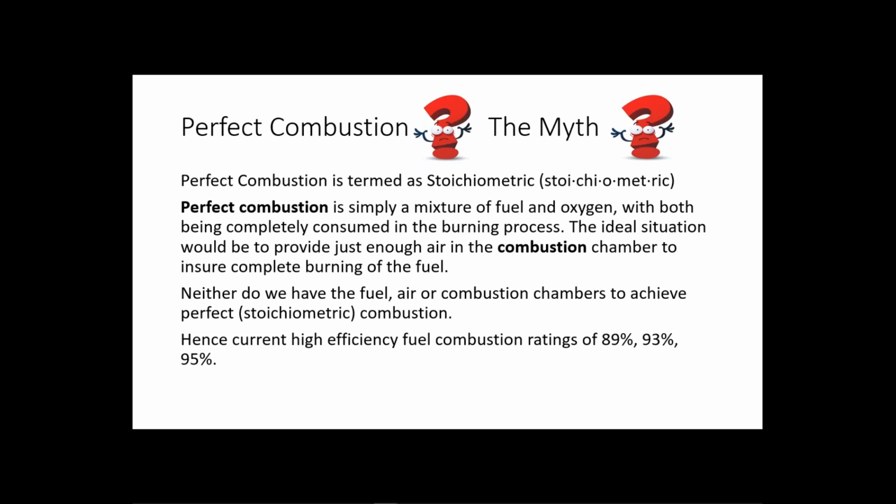The ideal situation would be to provide just enough air in the combustion chamber to ensure complete burning of the fuel, so that just enough air comes up again. Earlier you saw a slide that said without excessive excess air. Well, we're kind of handcuffed there. We're always going to have some excess air. Any excess air means that we haven't gotten to the stoichiometric level, meaning perfect. So neither do we have the fuel, air, or combustion chambers to achieve perfect, known as stoichiometric combustion.